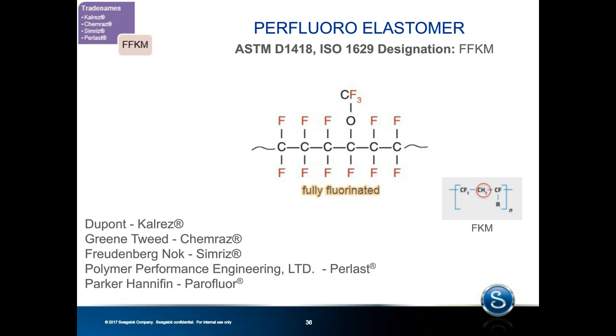If you look at my little box with FKM, we can remember that not all the combinations in the main chain were carbon and fluorine. We had some instances of carbon to hydrogen, which sort of presents the chink in the armor, so to speak, for FKM.